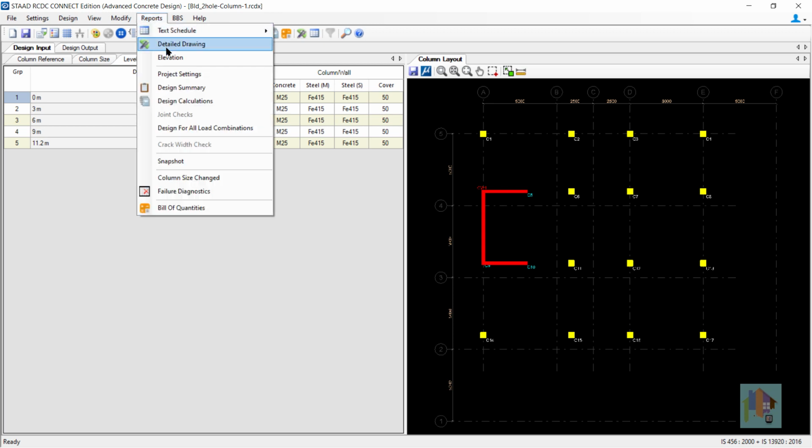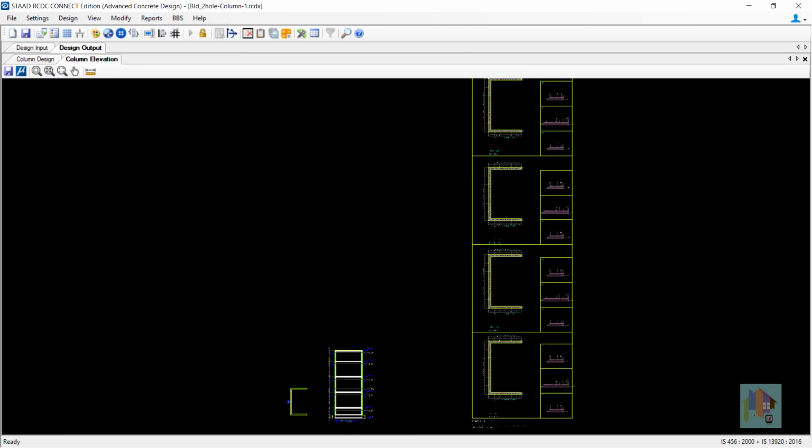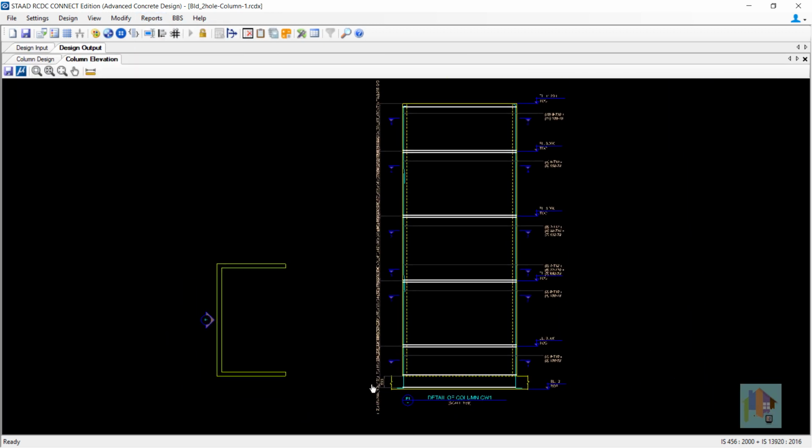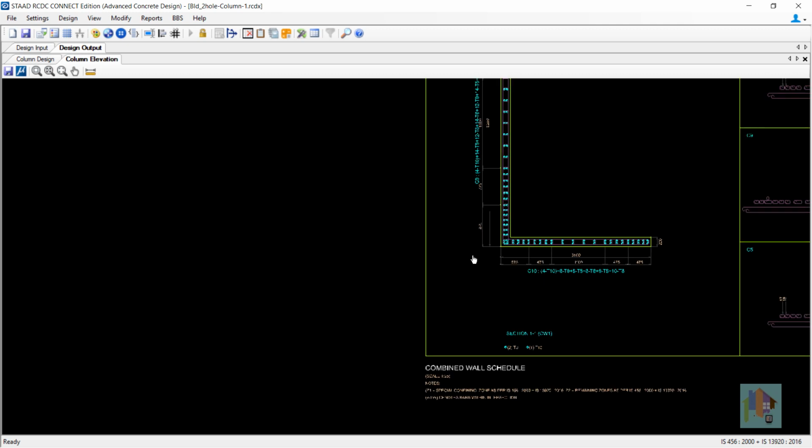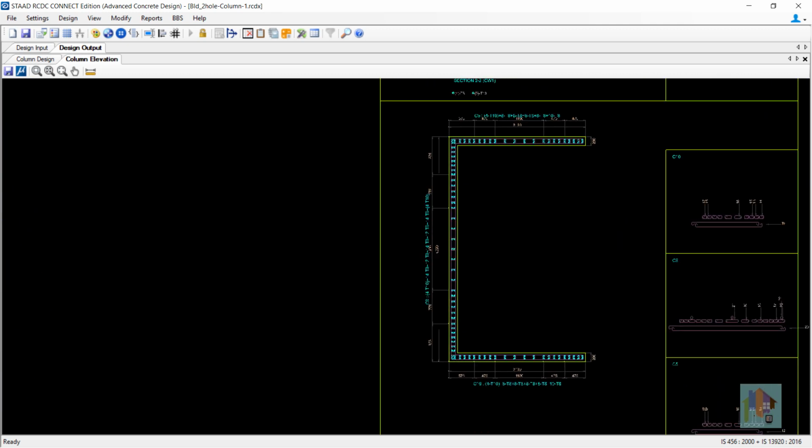Check the elevation view of this wall. No opening is considered in the final design. Also, continuous reinforcement is provided in the entire wall. If the opening is small, we can neglect that and use this approach to design the shear wall, though design results are not that accurate.